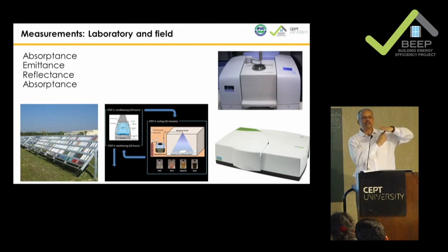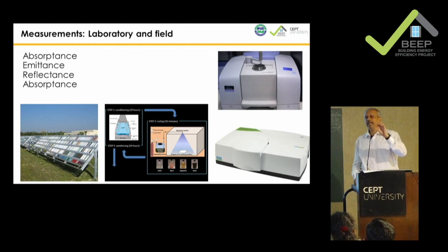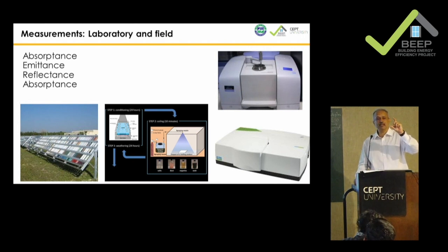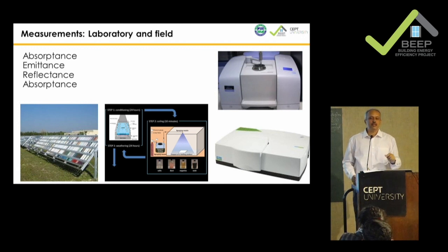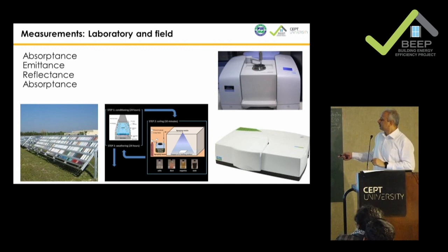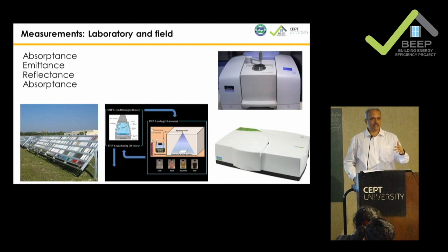We just need to look at the surface. Whether it's a paint or a coating applied on plywood, steel or brick, it can have the same SRI, because SRI is a surface property, nothing to do with the conductivity of the material.